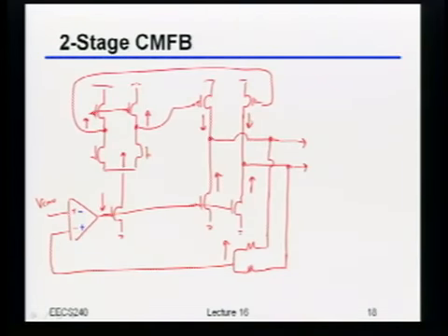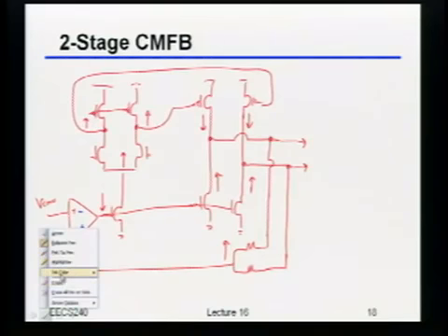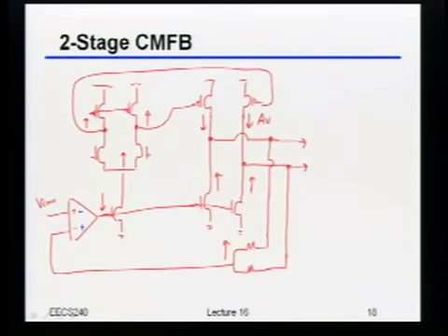So now, if we want this thing to be stable, what better be the case? So let's just label these things. Let's call this AVN times whatever VCM error, which is going to be, let's say, over here. And let's call this thing over here AVP times VCM error.